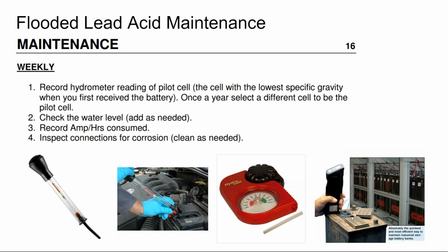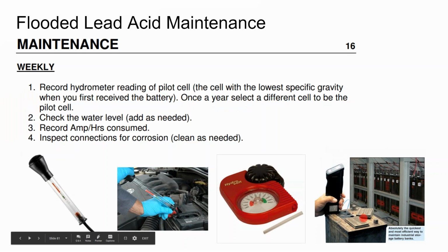I mean, the watering kit waters multiple points in the battery, and you only need to read one point in the battery on an annual basis, and then you rotate. So you can see this battery has 1, 2, 3, 4 holes. They would all get their little watering kit plug in them. And then generally for maintenance, you're just reading one cell. And then the next year you read the next cell, and the next year you read the next cell, and you just rotate it.